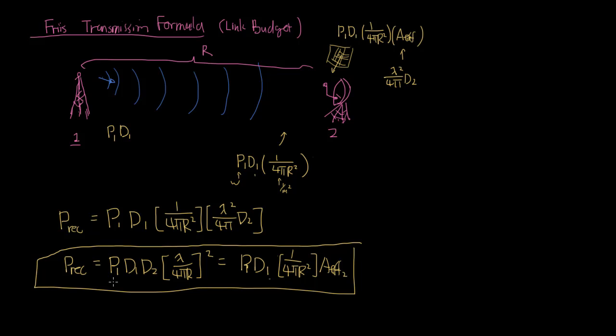physics works. A lot of our tricks for generating high power sources just don't work as well, especially from a solid state standpoint at these higher frequencies. So the only trick you have left is the directivity. And so to make up for these extra losses that you get by increasing the frequency, which gives you more bandwidth, lets you upload and download videos faster and all that good stuff, separately, in order for your link budget to work, you really need to boost the directivity of your transmit